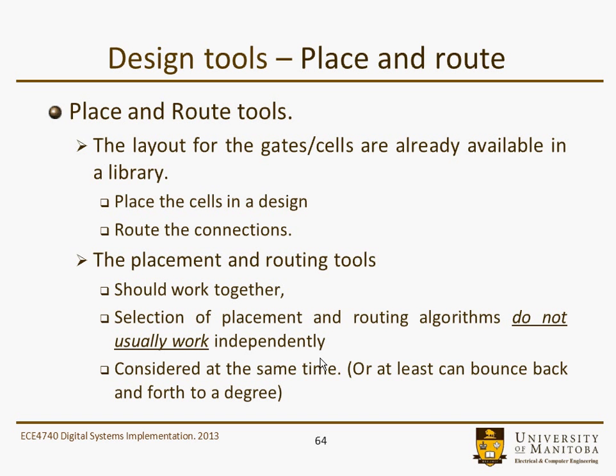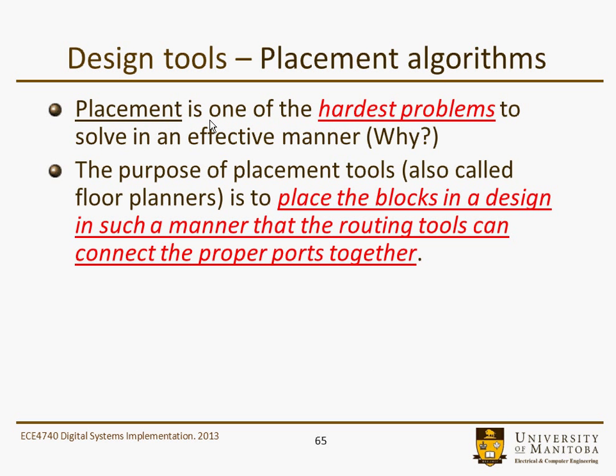More typically you might find a placement stage followed by routing, and if it doesn't meet the specification, that would be redone. Placement is one of the hardest problems to solve in an effective manner, and you might ask yourself why that would be the case, and we'll discuss that in a minute. But anyway, the purpose of placement tools or floor planners is to place blocks in a design in such a manner that the routing tools connect the proper ports together. And again, you want to do that probably minimizing something like wire area or overall area.